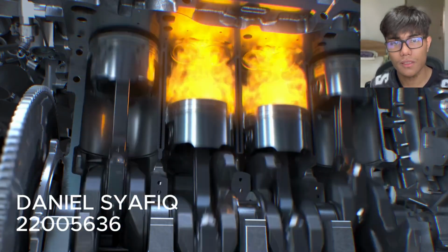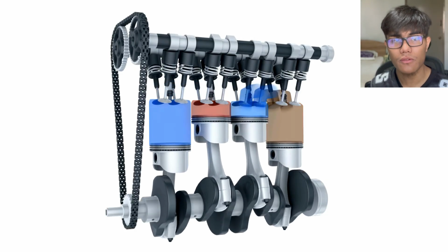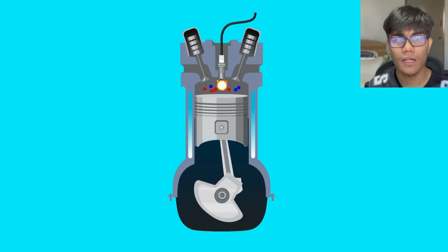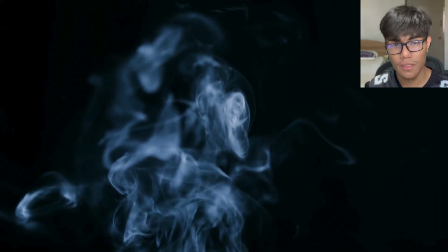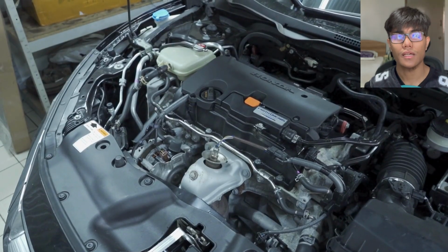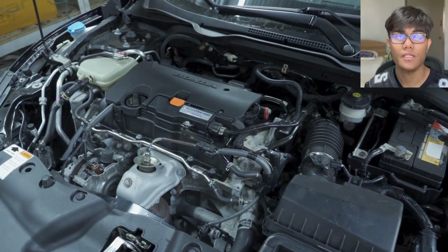Another important area is internal combustion engines. These engines, found in many vehicles, operate through a cycle of intake, compression, combustion, and exhaust. The first law is central here. The combustion of fuel adds heat to the system, increasing the internal energy of the gases. This high-pressure, high-temperature gas expands, doing work on a piston. This expansion is governed by the ideal gas law, which relates the pressure, volume, and temperature of the gas. The efficiency of this energy conversion is a key concern in engine design, and it's limited by the second law of thermodynamics, which dictates that not all heat energy can be converted into work. Some is always lost as waste heat.